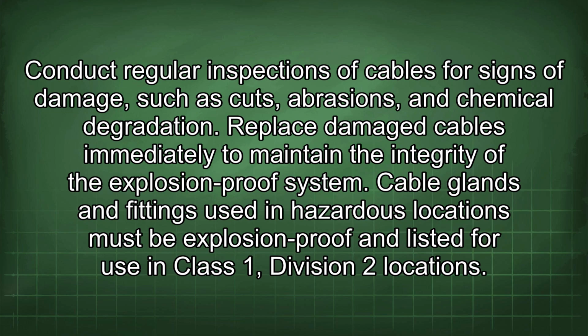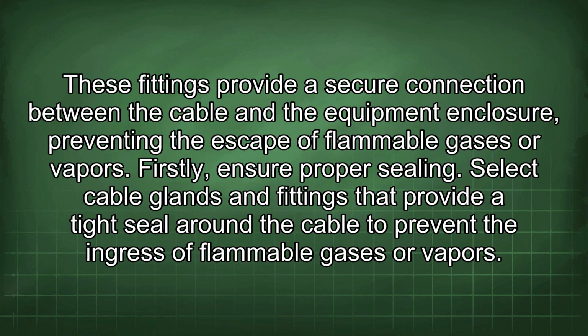Cable glands and fittings used in hazardous locations must be explosion-proof and listed for use in Class 1, Division 2 locations. These fittings provide a secure connection between the cable and the equipment enclosure, preventing the escape of flammable gases or vapors.